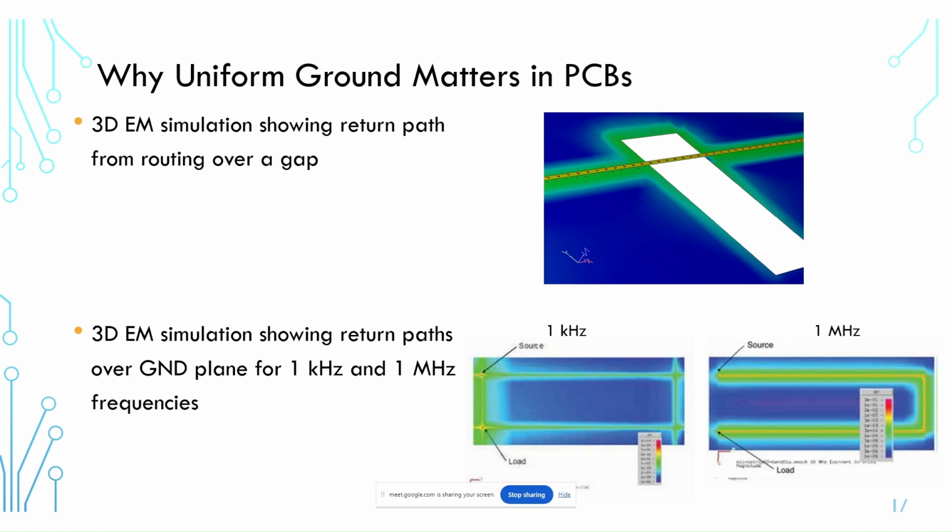And that arises because, if you're familiar with Fourier series, digital signals are really just a construction of a bunch of sine waves, and those sine waves can span down to very low frequency. So it is possible that there is some return current in this digital signal that doesn't really tightly couple below this trace, but most of it will couple below this trace. And so that's one of the reasons why we want to have uniform ground everywhere over here, especially if we're dealing with digital signals. Now, what about our analog signals?